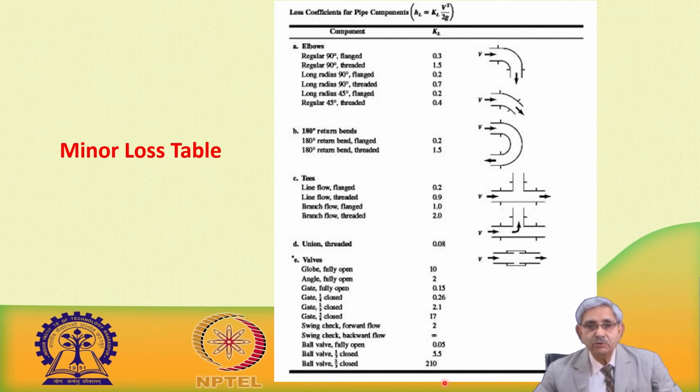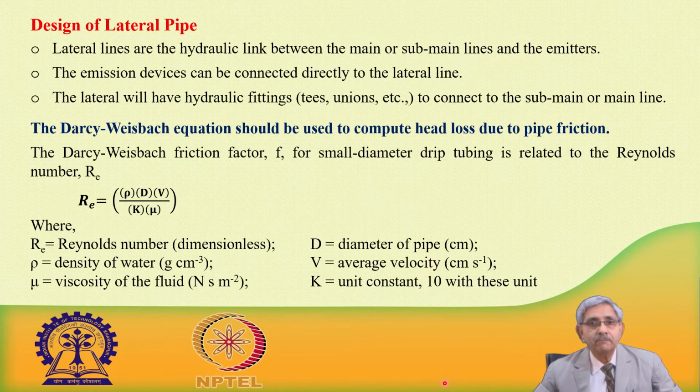So, in field situations we will come across these types of fittings. Maybe we are required to reduce the size of the pipeline or increase the size of the pipelines, so reducers, enlargers, such types of attachments and joints are needed. They cause loss of head, and that has to be calculated so that we can accurately get the value of head loss due to friction.